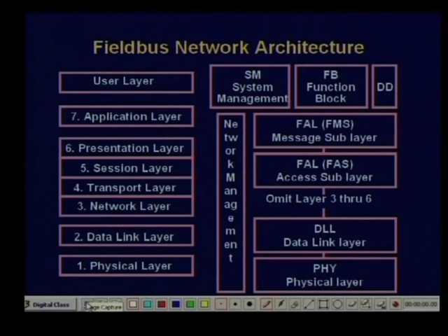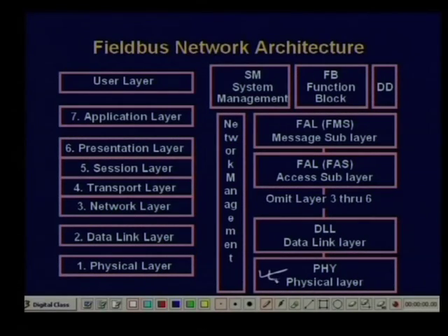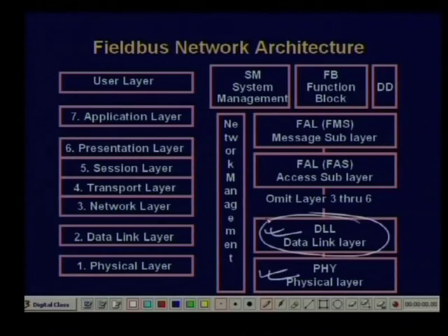So, therefore, it is good to remove the transport and network layer. Therefore, the Fieldbus network actually has very rudimentary transport and network layers, right. So, it has a physical layer, it also has the data link layer, which puts the addresses and ensures who will transmit when, say the medium access protocol etc., for cyclic and acyclic communication, which is also handled in the data link layer.